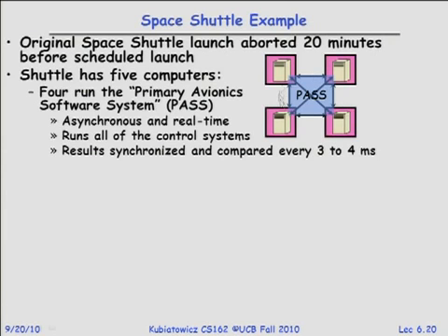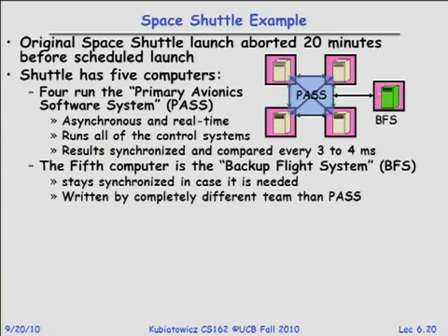So this was kind of an asynchronous set of 4 systems that were voting together. Here is the asynchronous system, and what would happen is there'd be this continuous comparison, and if there was ever a failure to compare in here, then you'd actually throw out the one that didn't get voted, and you'd still have 3 that were working well, and then this backup comparison would hopefully be continuously synchronized so that if things really went well, this guy was always ready to go.